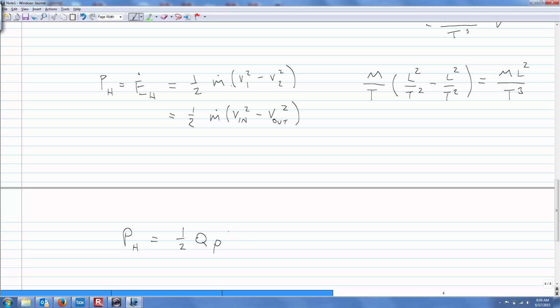rho V in. And I think we'll be able to measure V in fairly accurately. And all I think we're going to need to do is pace off a length of the river, throw a stick in. Somebody else is down at the other end. Sit there with a stopwatch, and you'll be able to know how fast the river's flowing, right? So there's your V in.